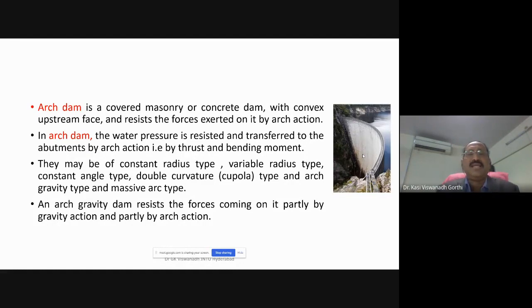Such a problem is not there in the arch dam. You can see here, you have arch action. As a result, the material used for the arch dam will be very, very less. The moment less material is used for the arch dam, less cement, less concrete, naturally, it becomes more and more economical. But the issue related with the arch dam is that you should have very careful design.